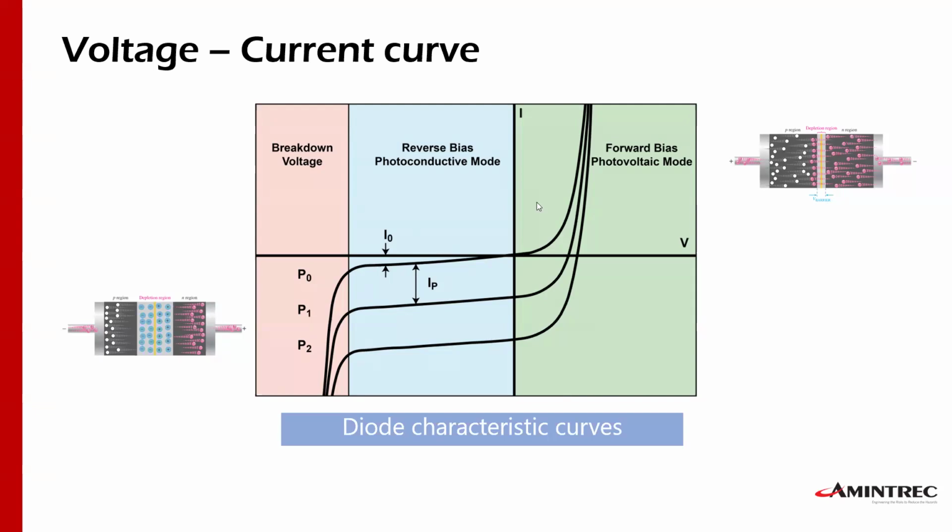You will see that when you have a forward bias, you're working in these two quadrants. You have the positive voltage right here at the terminal, and the negative at the N substrate. That is a forward bias, and that's pretty much this drawing over here.